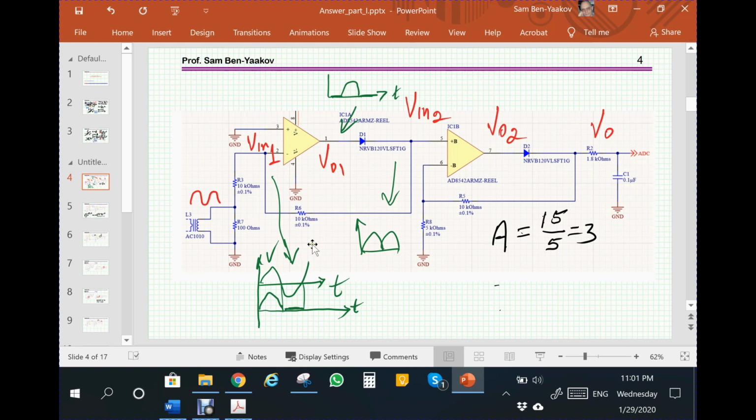So what happens is that we are now imposing a high voltage between the inputs, which should be, of course, virtual ground in the linear mode, but now we are pushing the amplifier hard into saturation. This will swing as low as it can. This is a single supply design, and this is a rail-to-rail amplifier. So this voltage will go down to approximately ground, not exactly, but close to ground, depending on the type of amplifier.